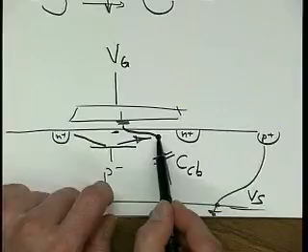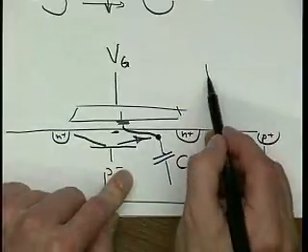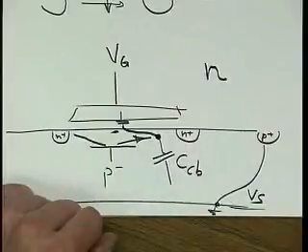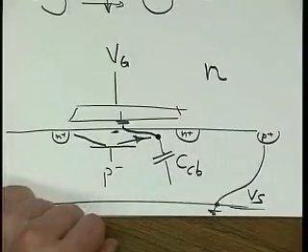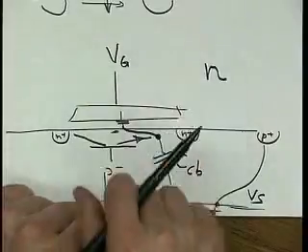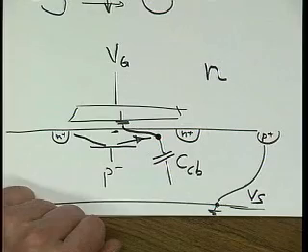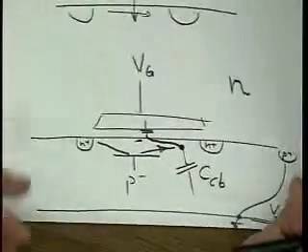Right? Well, this factor n is precisely the ratio of this capacitive divider. And the actual value, of course, varies depending on the doping and the oxide thickness and so on, so it's technology dependent, but typically it's around 1.5. Okay? And for our process also happens to be about 1.5. So that's why we get this factor of n.